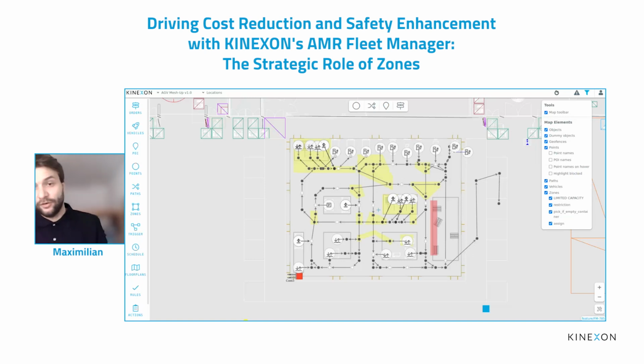So for the old fleet, the old robots where we cannot do much, but maybe just pause, resume them, and get their location, those request to enter an area, and we see if our fleet manager already requested the area as well. And if it requested the area as well, we pause the old vehicle and let the new vehicle drive through. As soon as the new vehicle, which is managed by our fleet manager, has left the area, the old vehicle is allowed to drive again.